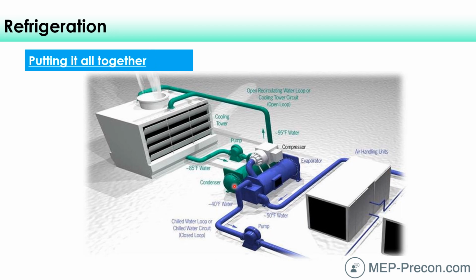That's how the BTUs travel from the air through this coil, through the water, through this refrigeration cycle here into the refrigerant. It boils the refrigerant, goes into the compressor, pumps it up into a really high pressure, high temperature, exchanges those BTUs within our condenser barrel. We get rid of those out of the refrigerant into the water. It goes out of our cooling tower, and that's how we get the BTUs from inside of our space to outside of our space within a water-cooled hydronic system. Whew, that was a lot.